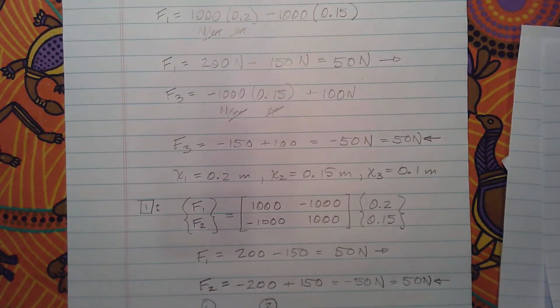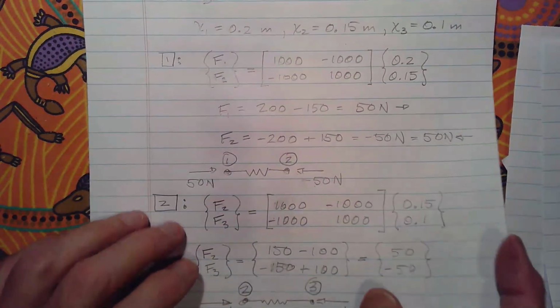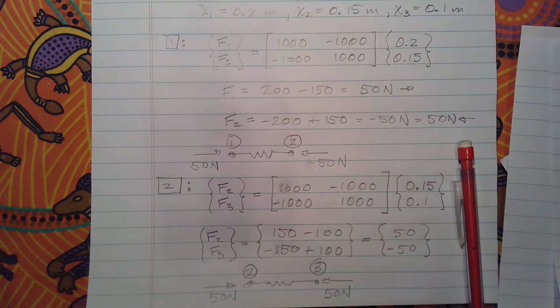I think an interesting thing that you could do with this, there's several things you could do. You could try 3 elements if you wanted to, and you'll have a bigger global matrix. If you have 3 elements, you're going to have 4 nodes, so you'll have a 4x4 system instead of a 3x3 system. And you'll find that if you use the same stiffness, your nodal forces are less. So that'd be one thing to try, just to get some experience on your own.